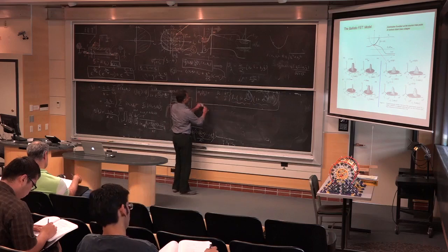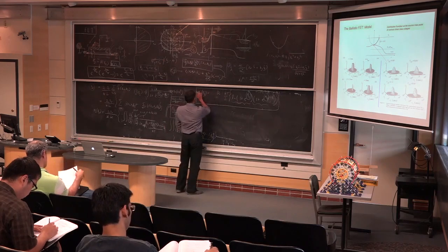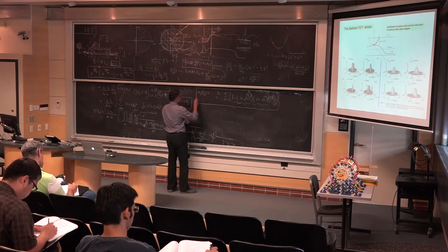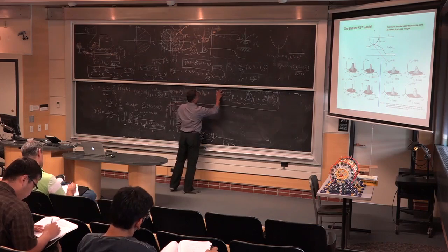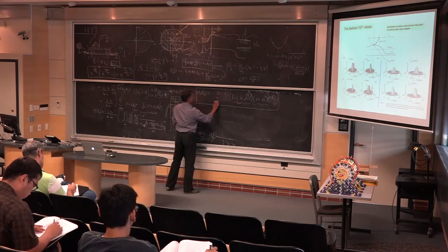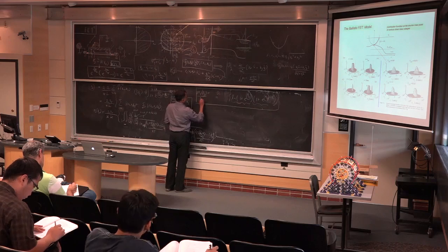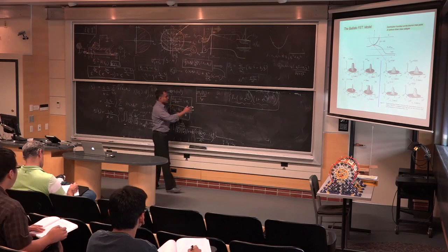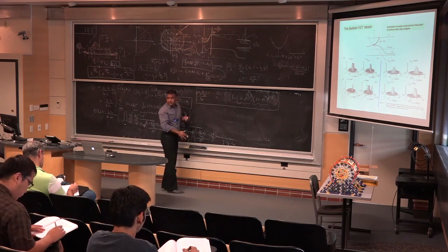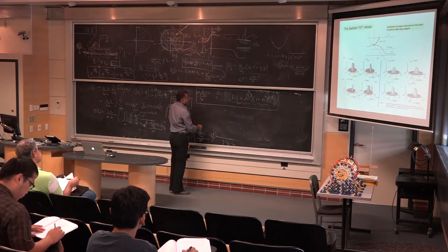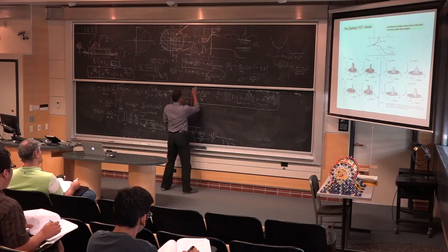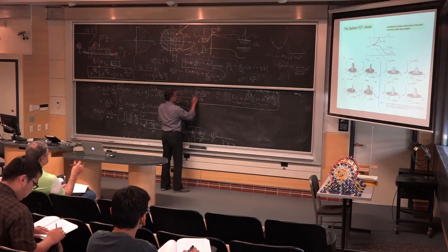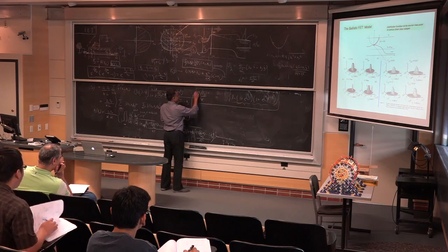So you can again retransform all this stuff. Take the 2 here, and 2. And you remember, we can absorb this D naught and kTs and all that into our quantum capacitance, quantum carrier density. So we just write it like that. Right? And then you exponentiate both sides again. Okay, you exponentiate and all that. So this becomes, again, I mean, I'm doing all the details again, ln, natural log of e to the power this whole thing, right?